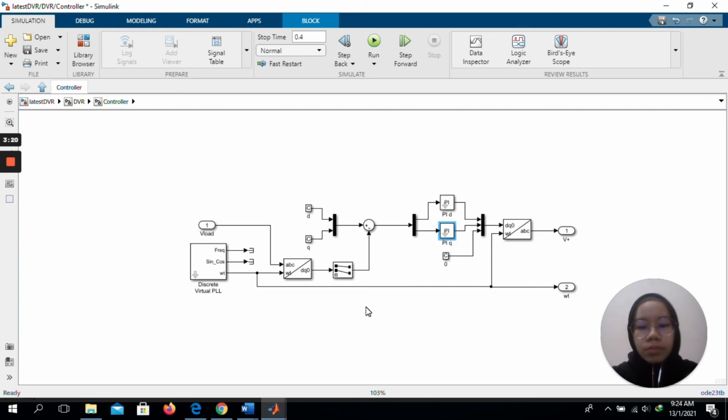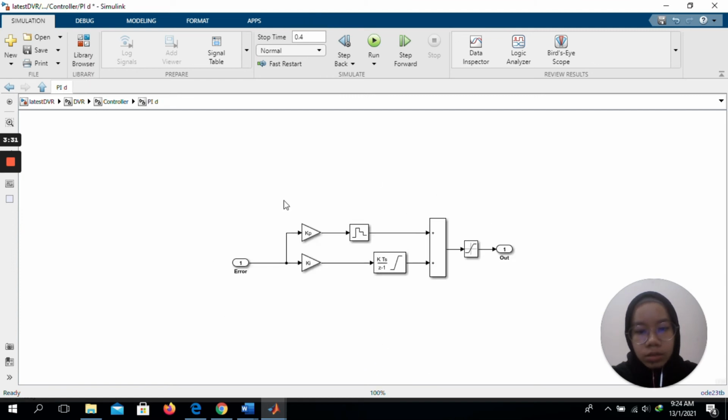This here is the PI controller that we have built. This PI controller is a feedback controller which drives the plant using the error difference between the output and the desired set point, and the integral of that value. All the gains selected are used to tune out the error signal in D and Q, so the signal is stable and will respond to the system.